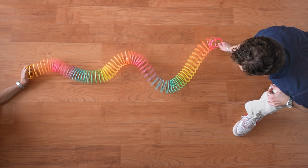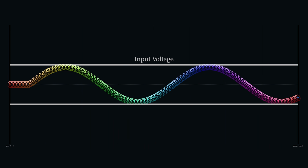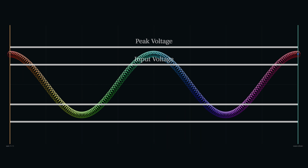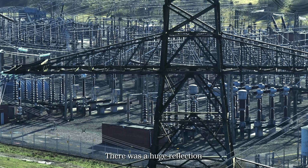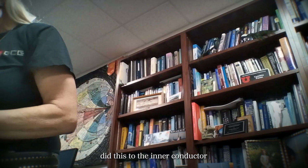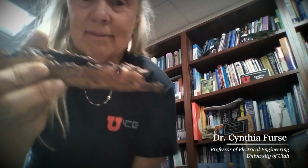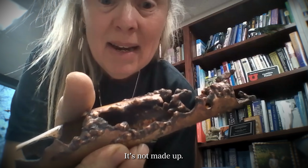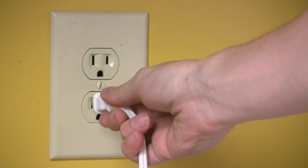In electrical systems, this standing wave pattern can be a big problem. That's because if the reflections in your transmission line are bad enough, the peak voltages can reach up to twice the input voltage. And if your line isn't rated for that, well, it burns out. There was a huge reflection, and its powerful standing wave did this to the inner conductor of that transmission line. This is the effect of the standing wave. It's not made up. In most electrical systems we're used to, this isn't too much of a problem.